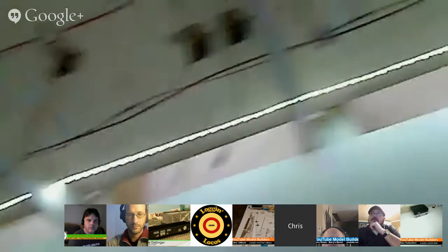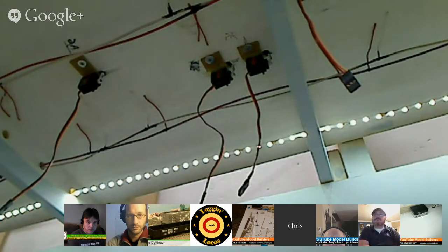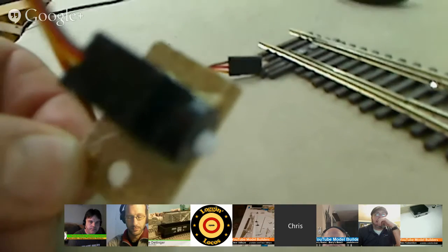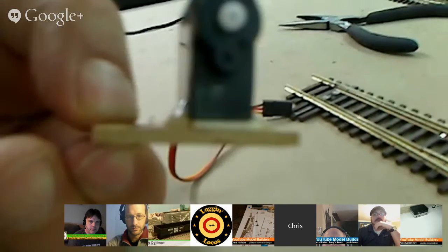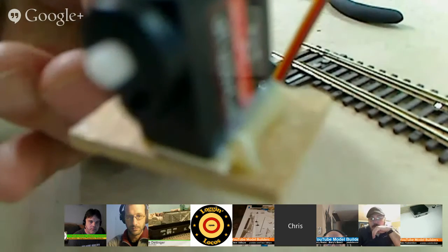What I like about the Tam Valley system is the laser cut board brackets. You can buy them assembled or unassembled, and save a few bucks that way. The servo mounts over 2 screws mounted to your layout. Then the board has all the controls on it, so you can program and set your endpoints, plug it into your DCC system, and send a switch throw command that sets the 4 adjacent addresses. But you can save money on the brackets. Doing what he did probably saved him $4 a turnout.